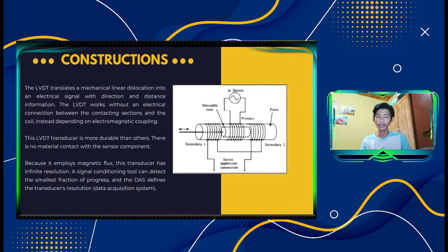It consists of a cylindrical former that is surrounded by one major coil in the hub of the former and two minor copper coils on the surfaces. The number of turns in each minor coil is identical, but they are wound in opposite directions, clockwise and counterclockwise. For this reason, the output voltage will be the variation in voltages between the two minor coils.